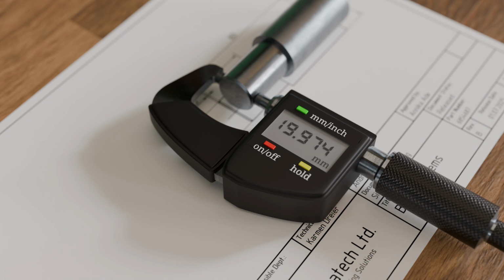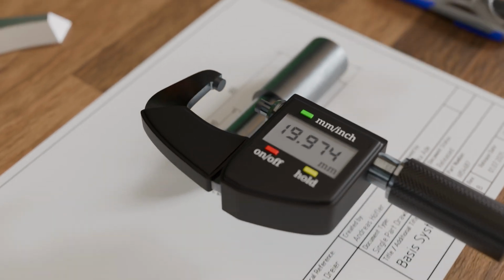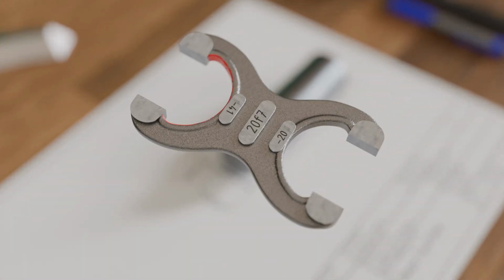However, in mass production, the use of a micrometer screw gauge for cost-effective inspection of dimensional accuracy is not particularly suitable due to the time required. Therefore, similar to gauges for bores, there are also special limit gauges for shafts for quick verification of dimensional accuracy. These are called limit snap gauges.